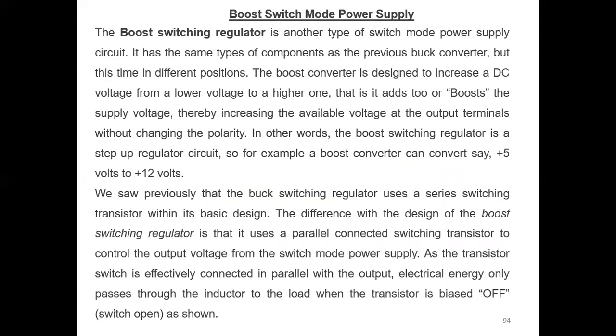So next one, boost switch mode power supply. The boost switching mode regulator is another type of switching mode power supply circuit. It has the same type of components as the previous buck converter, but this time in different positions. It is designed to increase the DC voltage from a lower voltage to a higher one.